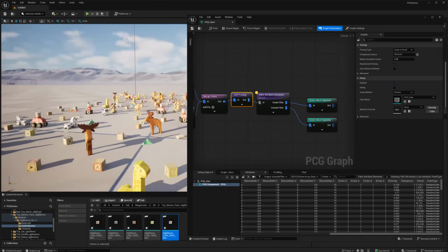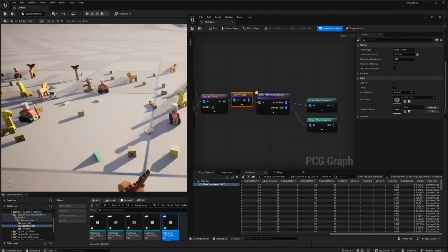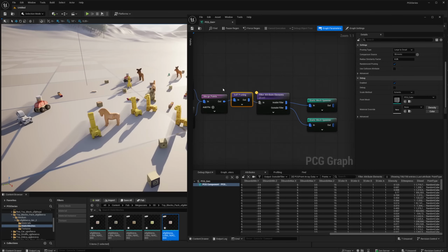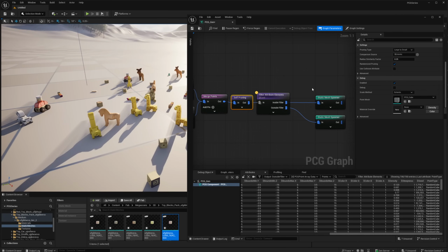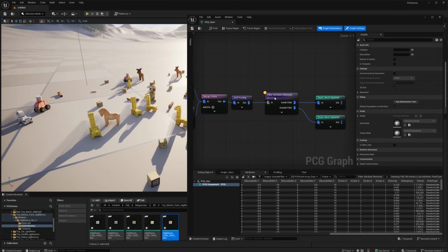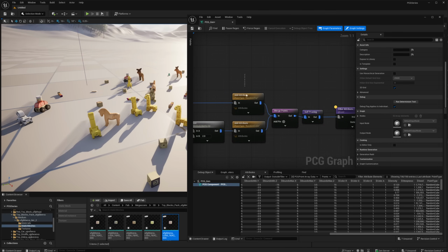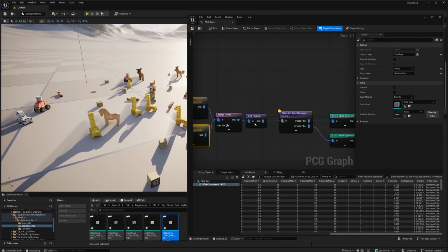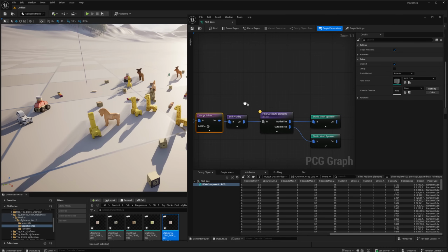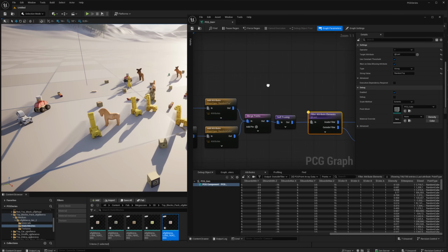We have the full self-pruning result for all the points, but we are now spawning two different types of meshes from two different sets, which we achieved by having this attribute having a different value to them. So after we merge them, we have a way to split them again.